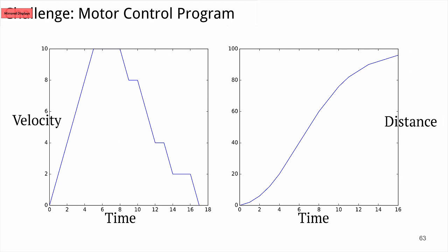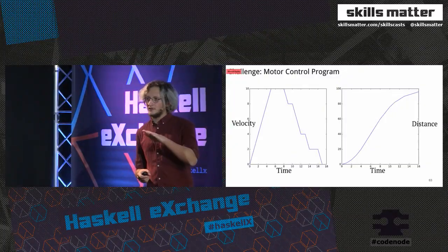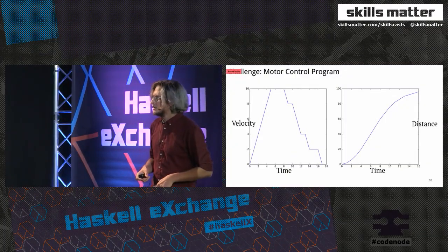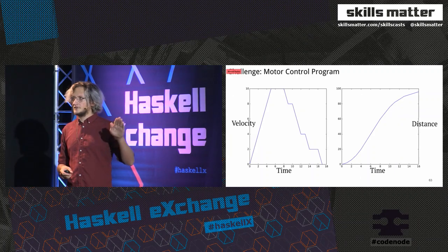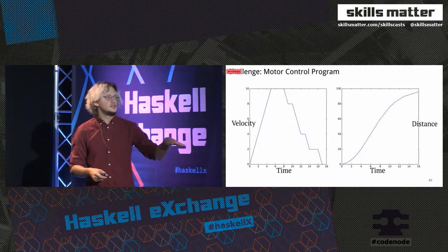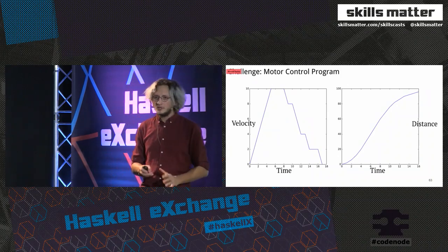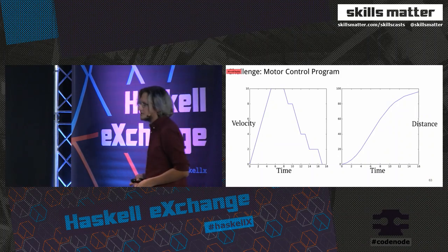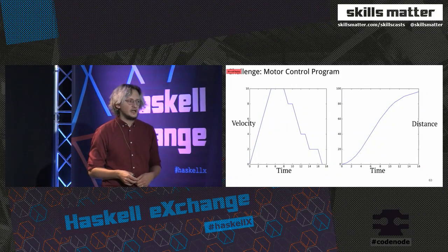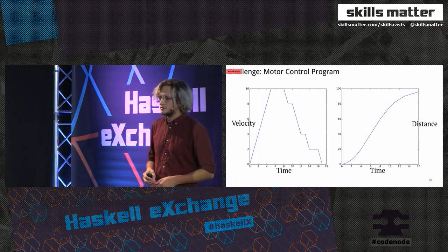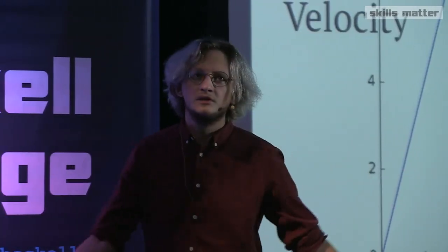So the example was, imagine a stepper motor that controls a solar panel or an antenna pointing unit. In order to move a solar panel and point it to the sun to get more energy, we first need to accelerate the motor for some time, then move it with a steady speed, and then decelerate. It is really important that this movement happens correctly, in that the maximum speed is not exceeded and the maximum acceleration is not exceeded, in order to not introduce any disturbances in the whole system.